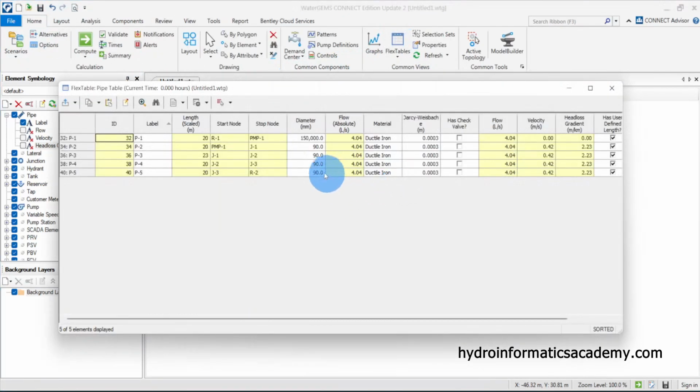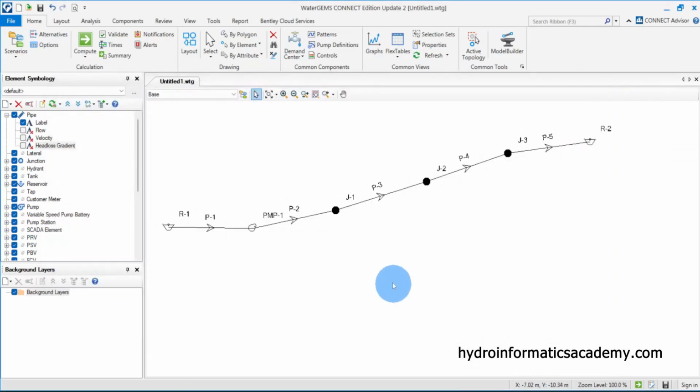Let me go back here and select, at least let me take it back to 1110, and also this one. Of course, remember, you need to use the internal diameter. For now, I'm using the OD. Of course, this is the simplest way, but you need to use the internal diameter. That's very important. So let me close this. So from here, let me run my model.